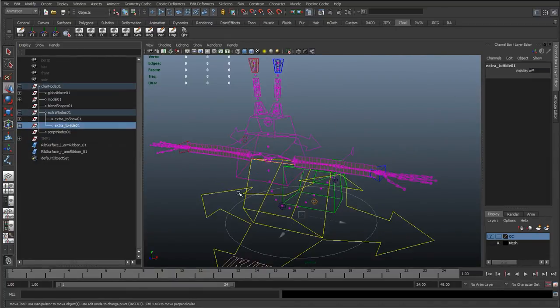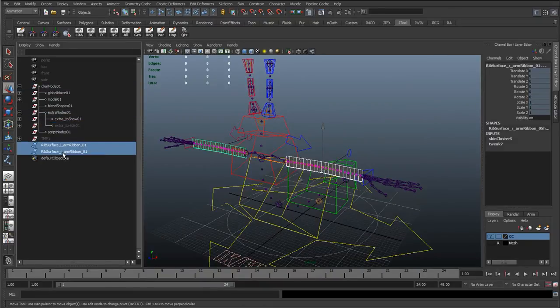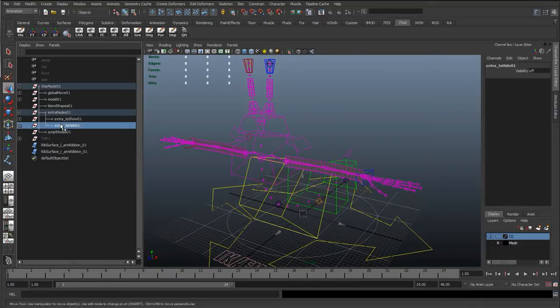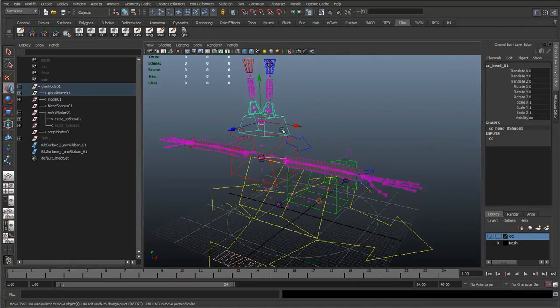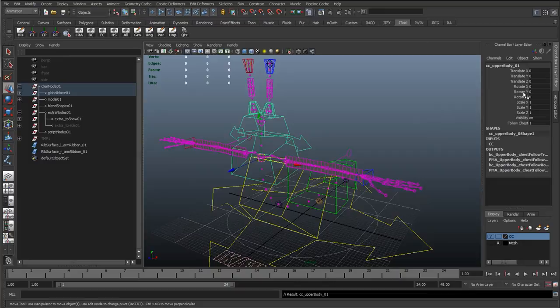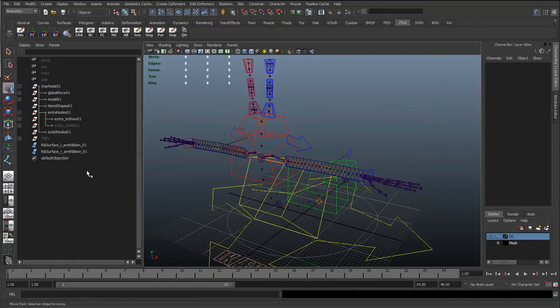And because the origin of the group is the same as the grid, we're not going to get any offsets by unparenting it, and there's no constraints with this group. It's just a hidden group, so it's not going to have any problems unparenting these and reparenting them. I wouldn't recommend that for other parts of the rig. If you don't want it to work on this curve, you won't want to unparent that, because that's got rotate offset groups with values, different groups with constraints in there, so we don't want to mess with them.